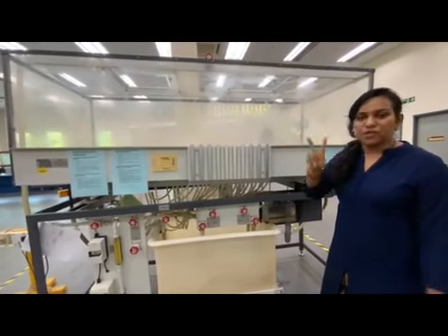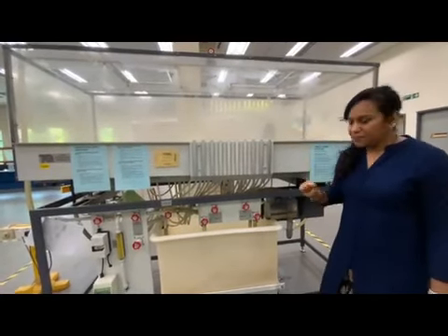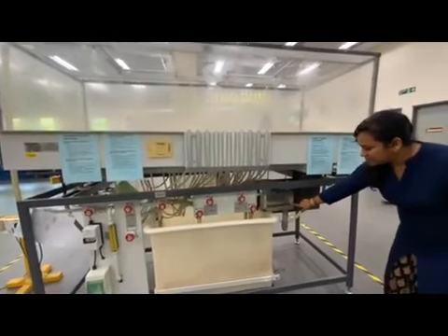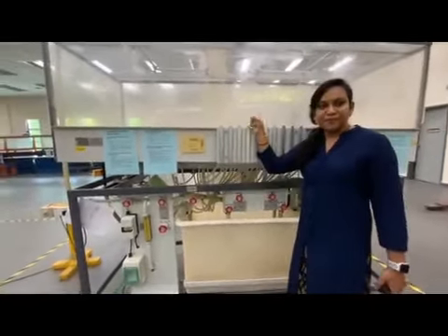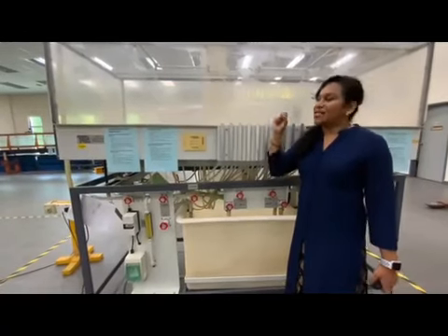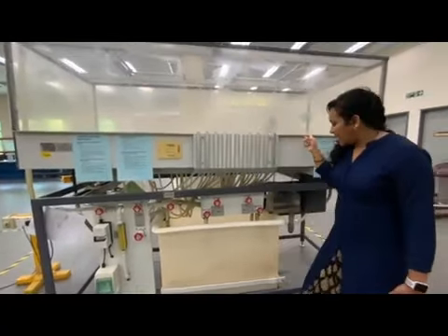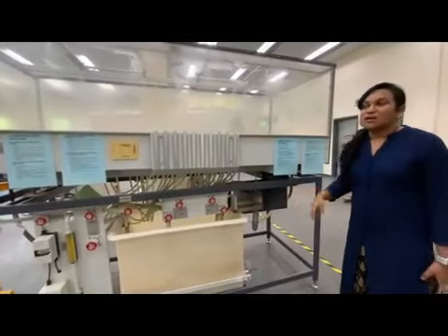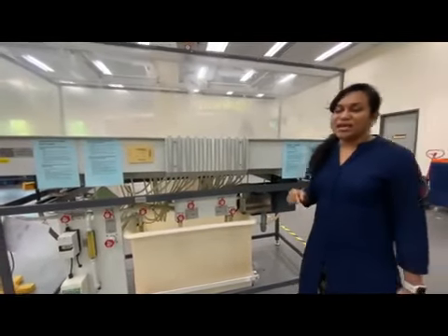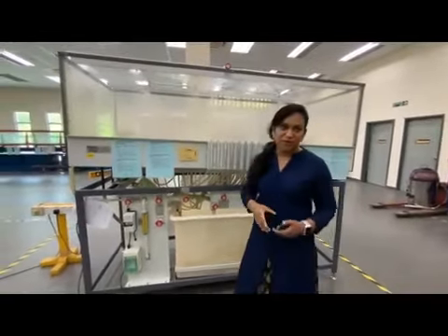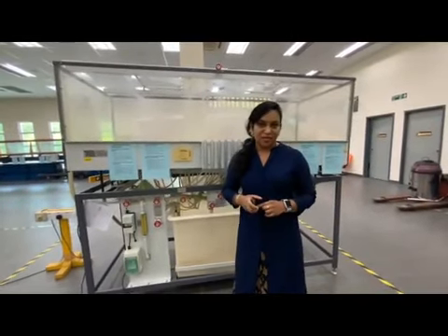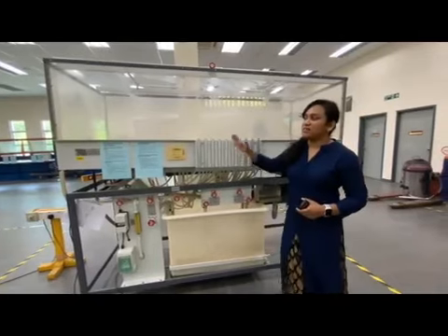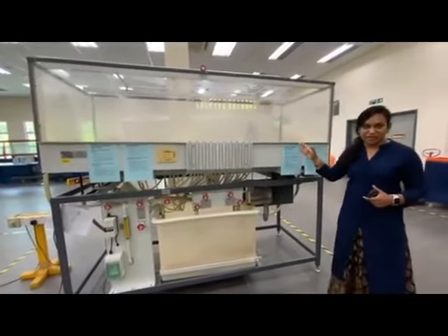For the next measurement, multiple rainfall, we'll be doing the same experiment: let it rain for 2 minutes, and then we stop and do the measurement for 2 minutes, and then we switch on the pump again for 2 minutes, and then switch it off again and re-monitor. So that is how we are going to do the experiment for multiple rainfall within a catchment. That's about it on the theoretical part of this particular experiment.